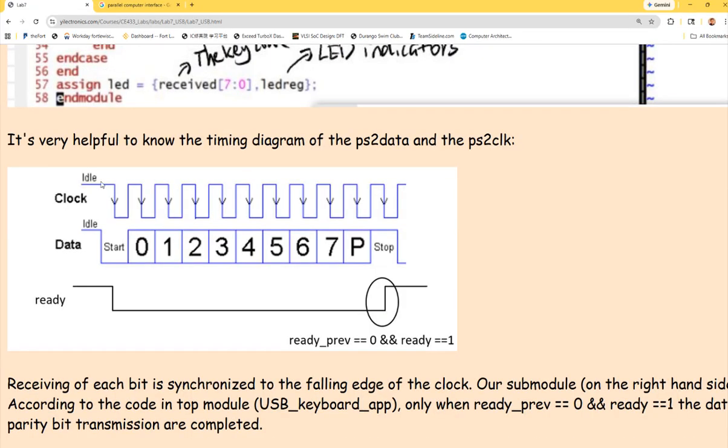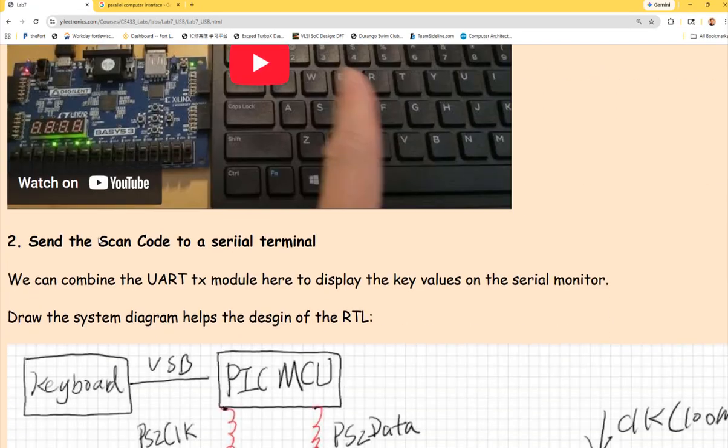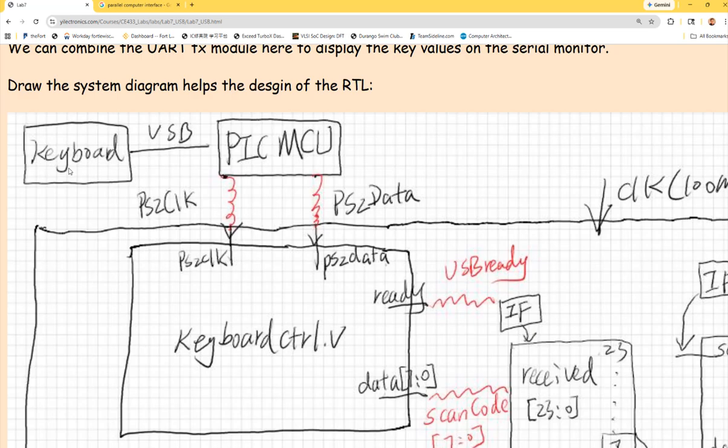And no matter what, as long as you power up your FPGA, your keyboard is being powered up. There's no external power, right? So the FPGA is being powered up. The 5 volts will be delivered through the USB to the keyboard. The 5 volts, right? USB is always 5 volts. They have a common ground. They have everything. There's no desktop involved. It's just the laptops.